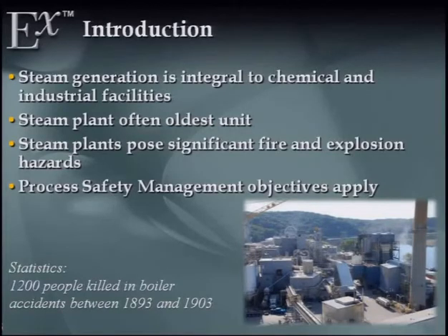Everybody relies on it. Because of the high temperature, high pressure steam involved, everybody's aware of that hazard, but there are also significant combustion safeguards with the firebox and burner systems. The process safety management objectives that you apply to the rest of the plant should still apply to the boiler house.